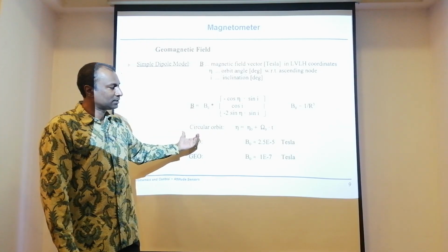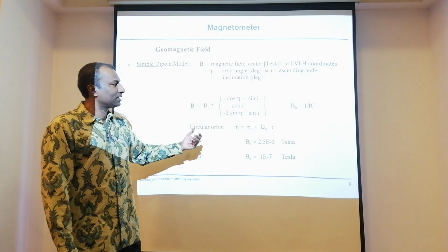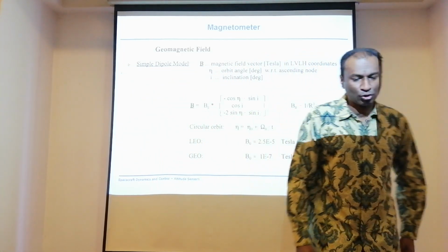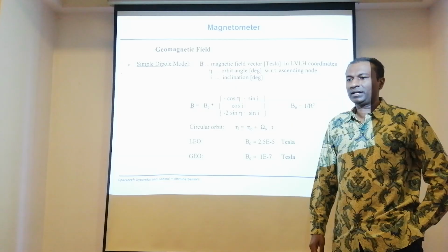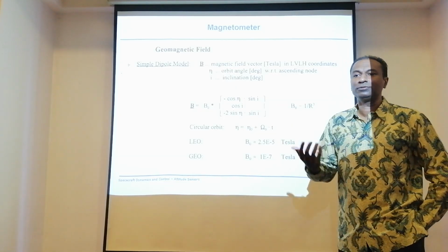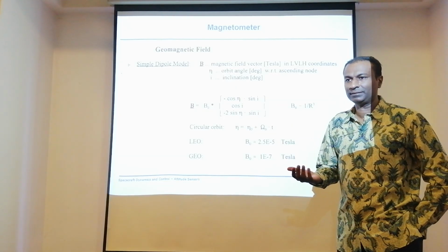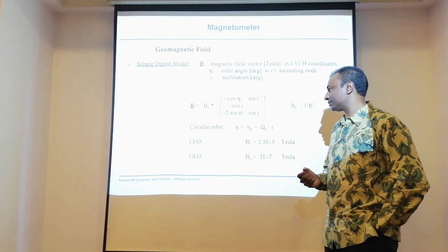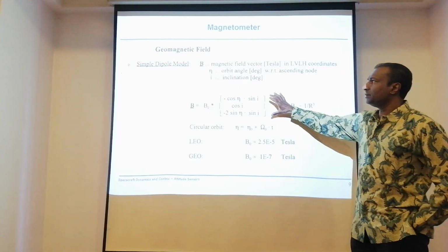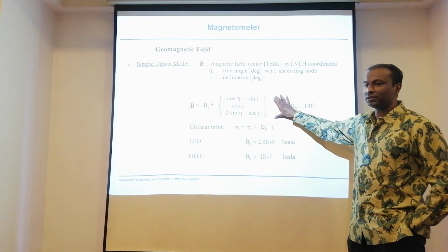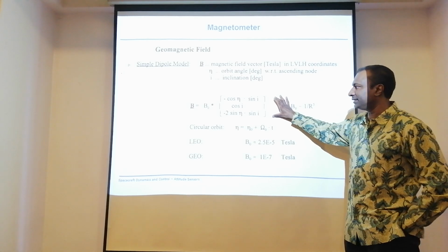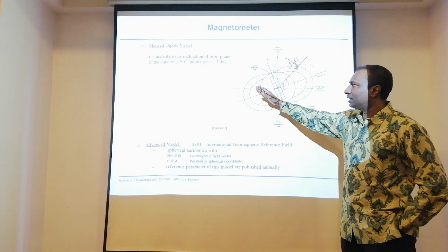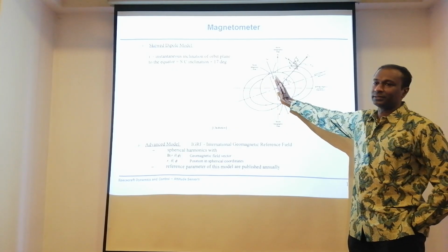It is a low orbit, low Earth orbit, or geo orbit. This can always be used. But again, when you're already flying in a geo orbit or geostationary orbit, well, I would say magnetometers might not be a good choice of sensor, because it's going to give you quite weak attitude sensing capabilities. So again, in this case, we use a simple model for estimation. But again, go on. There's another model, basically a tilted model. This, because as you know, we are tilted.